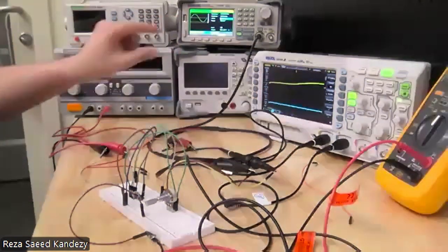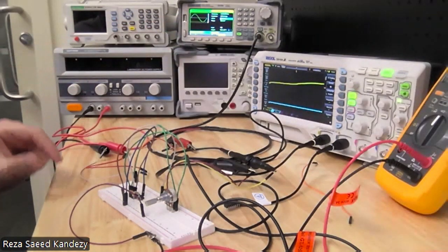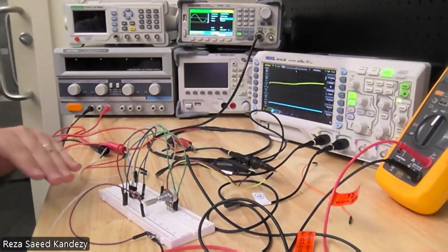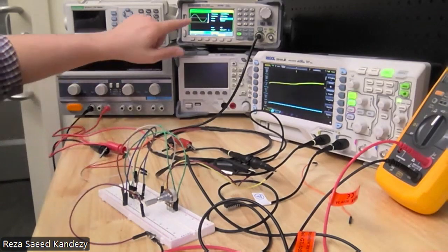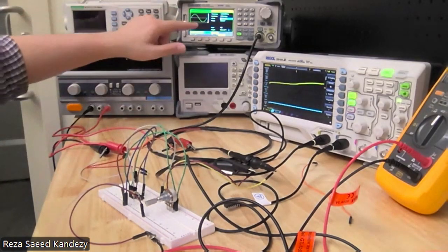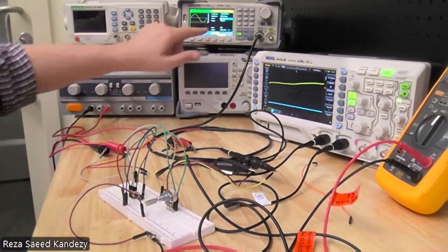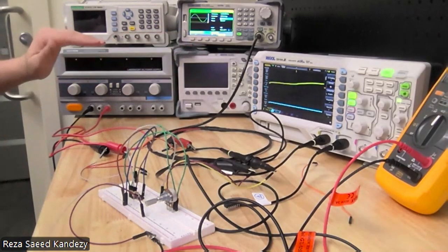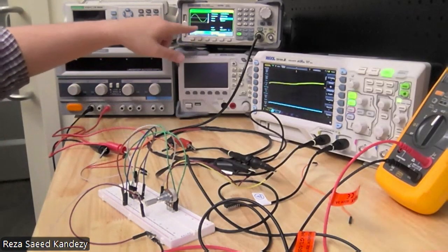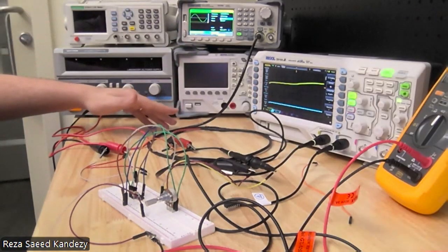Okay, that means on that negative part, your op amp is going to be deactivated. So the signal is going to be chopped. Okay, so I offset the 100 millivolt, so I make sure that through the time, I never go below the 0 line.